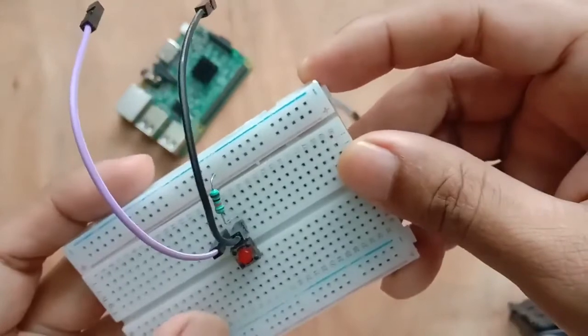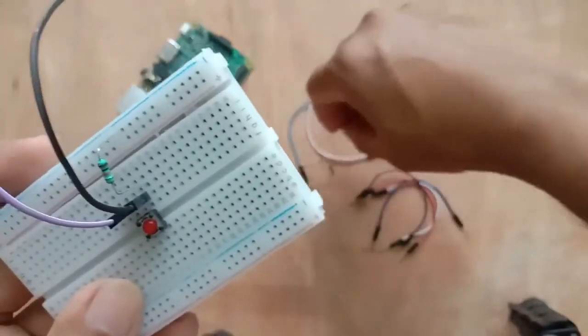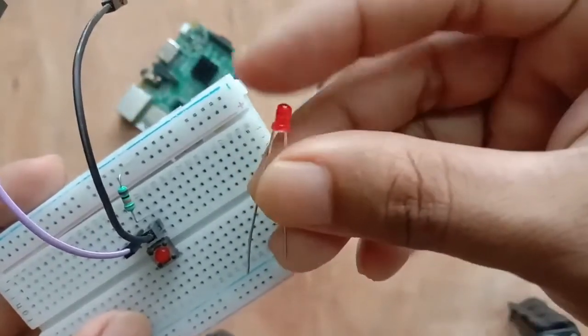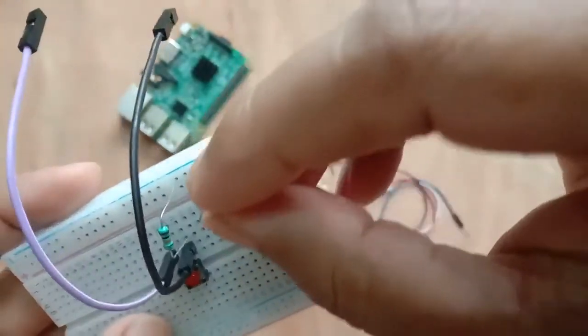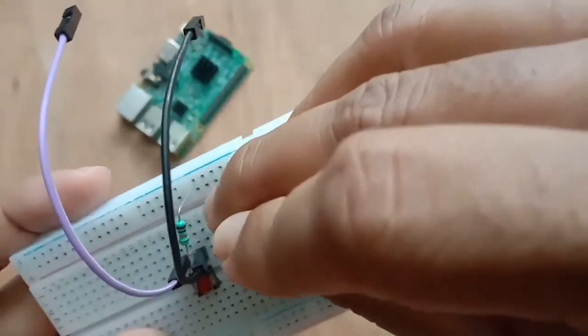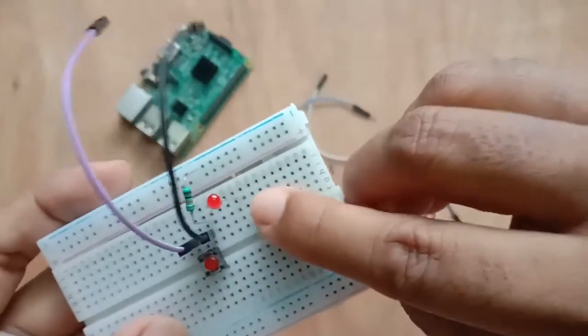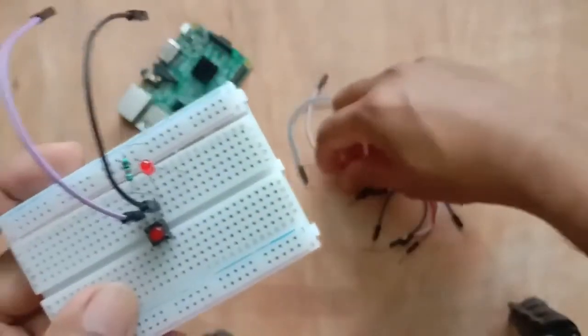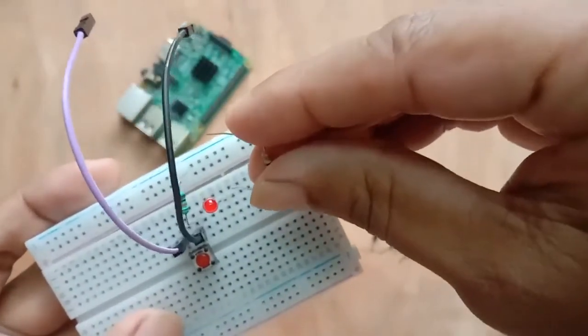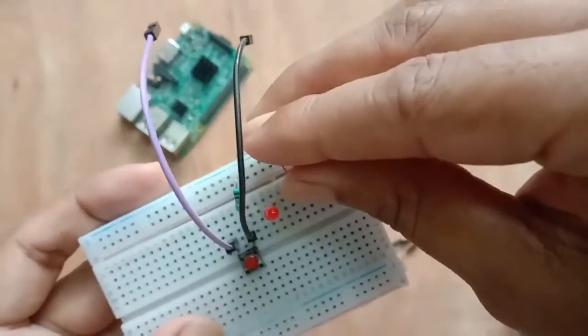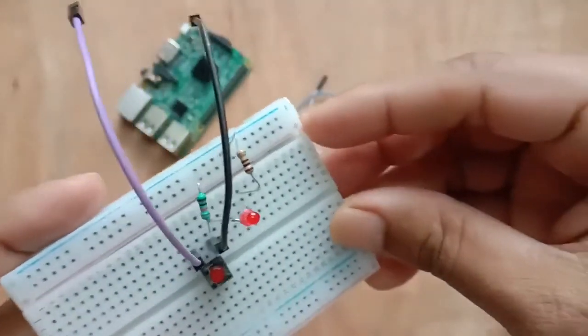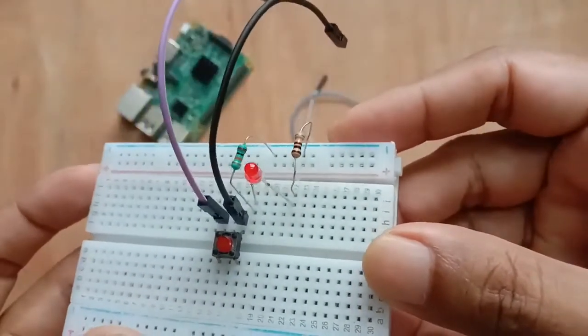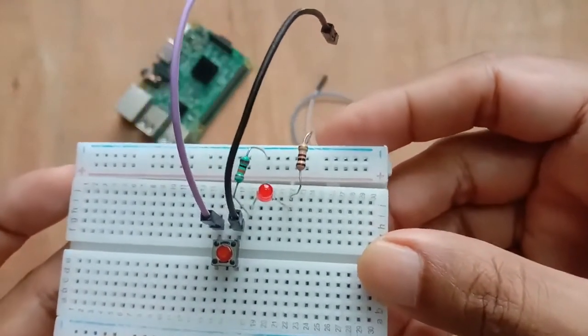So here it is. And then we will use the LED. Please mind the anode and cathode. The longer side should be on the positive side, and here is the positive side, and here is the negative end, and the negative end should have a 100 ohm resistor and go to ground, just to limit the current flow through the LED. So this is how our circuit looks.